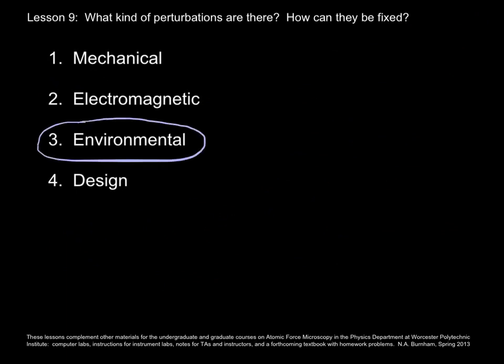You should think about the environment that you're creating for your AFM. You want a stable temperature. A temperature change that's small to us can be very big to AFM. Just a few microns of drift, well, you can detect that with AFM. So have some means of keeping the temperature in your lab stable. That's another reason that basements are good.